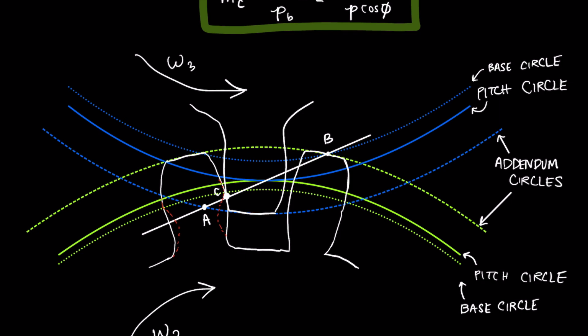Okay, so our backlash is this gap that exists between these two teeth. So this gap right here. And if I were to now reverse the direction of this gear, take this omega 2 and go in the opposite direction, then this backlash, that gap, would be taken up by this gear tooth moving until it contacts the other side of the gear tooth on the top side.